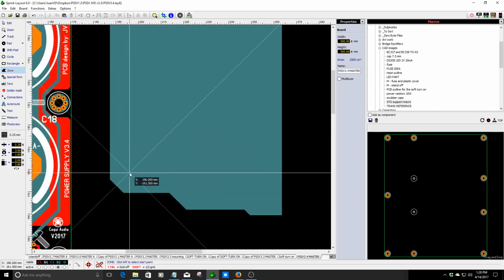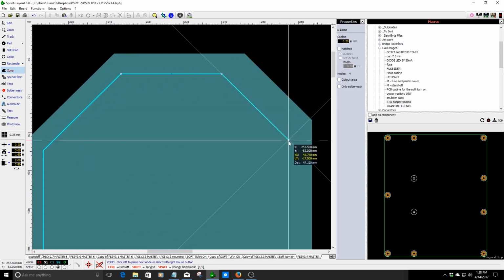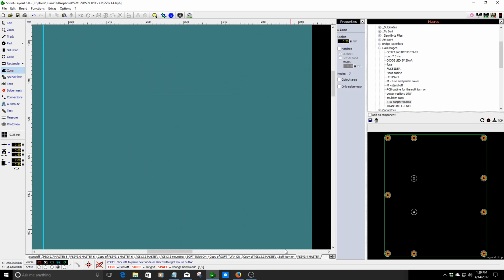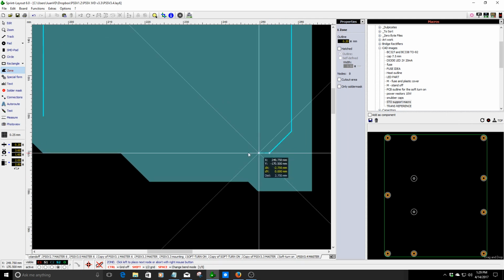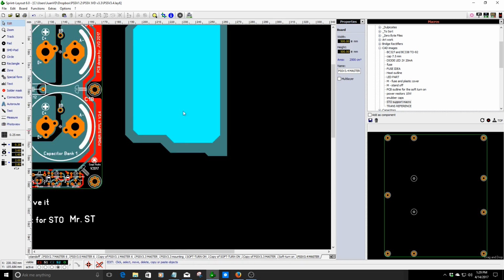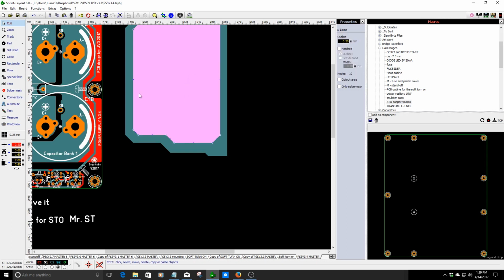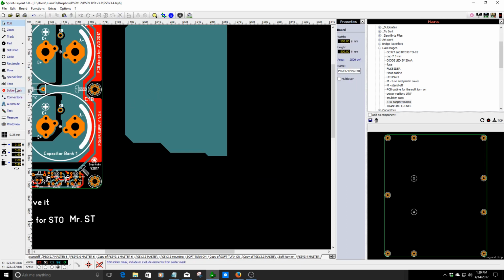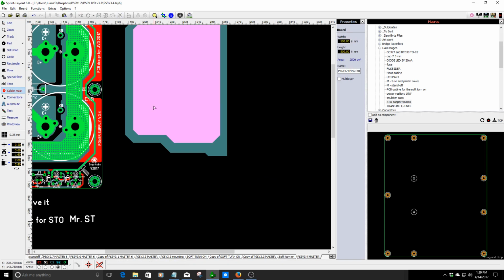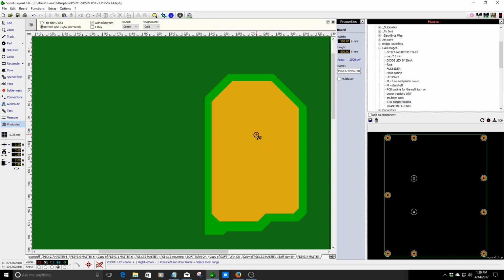I'm going to make the hatchet or solderable area, but I'm going to make a hatchet. Sorry about that. Okay, here you go. Just something quite fast. There you go, that is the solderable area. What we usually do is turn it into copper, and then I select the solder mask to apply a solder mask to that particular area, and now that area is going to receive solder.